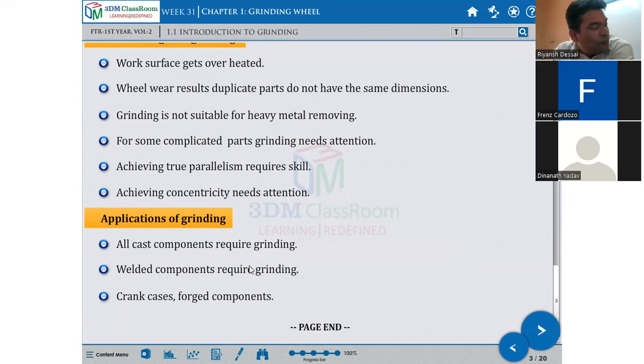If the component is rotating, like a shaft, you cannot join it by welding. If you weld it, there will be a bend, there will be a change in the shaft dimension. Once it bends and you rotate it, it will twist out of balance. Then in that case, you have to put a flange, a coupling, and join it. Right.